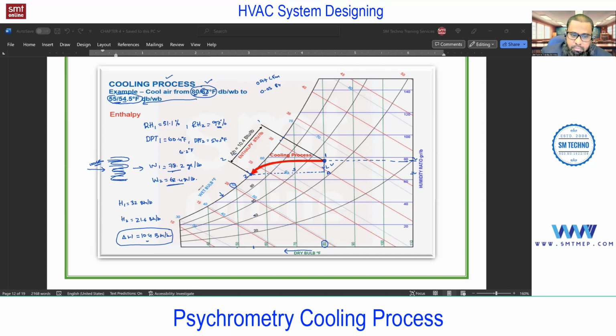At the same time, I can see that relative humidity also increases. Still, the specific humidity ratio has decreased. But that is an important point, what we discussed previously. Yes, it's a reverse case. I mean, temperature decreases, no? You see, that depends on the temperature. This RH level, you are asking: this W2 decreases, but the RH increases, right? Yes. But based on what? Based on the dry bulb.